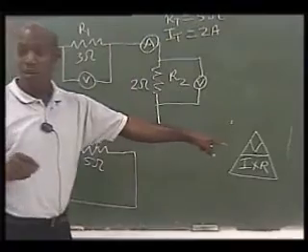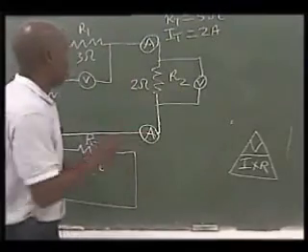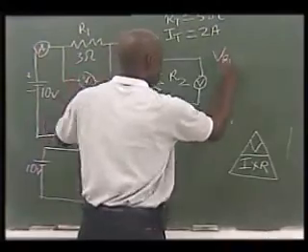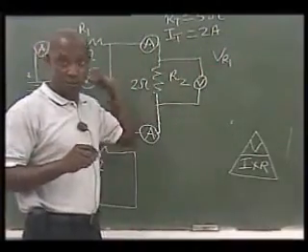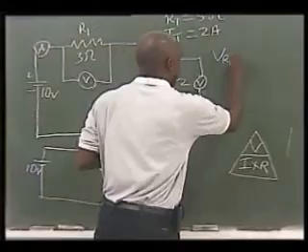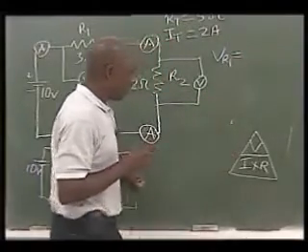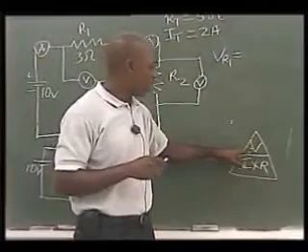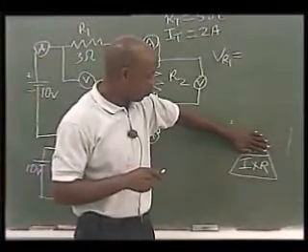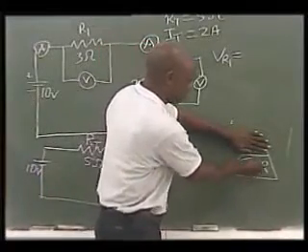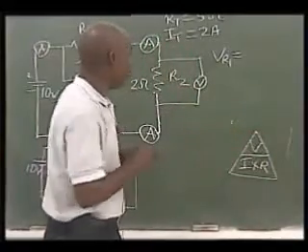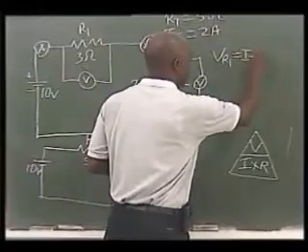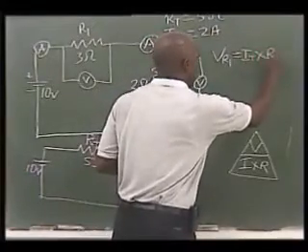Again, we're going to be using Ohm's law, and we're going to say that VR1, which is the voltage across R1 resistor, is equal to, come back to our friend here, we wish to find the V. Okay? We're going to block out what we don't know and simply multiply the current times the resistance. So that's going to be IT multiplied by R1.